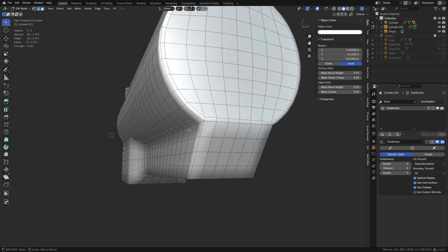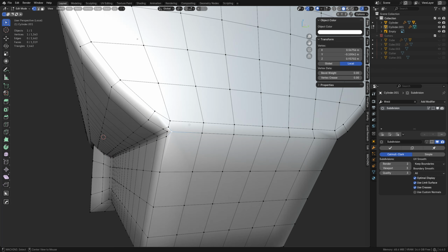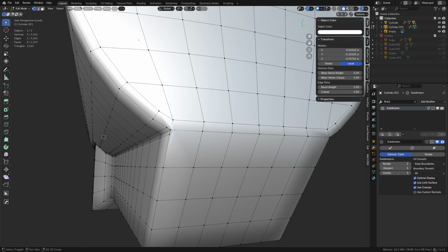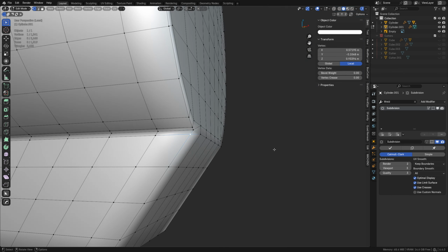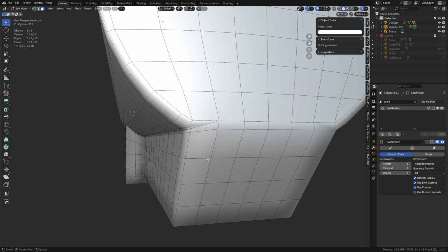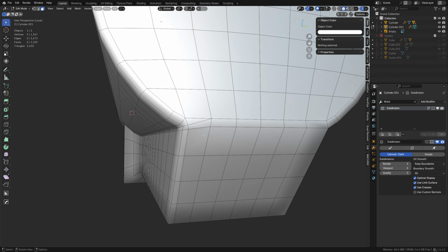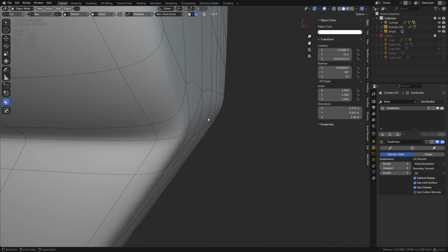Or you can do a bevel in that area, something along those lines, because this is still completely able to be beveled. We get something like this going. This kind of corner will fall apart. You can't just merge it like that. You have to pull these apart like this, right? And this one has to join to there somewhere, more than likely. Something like that. And then that will subdivide, but it's going to eat into it like this, right? So then this means the topology is not quite what we need, and we would need maybe another holding edge here. You see? That creates another quad there. And yeah, there are little tricks like this all over the place.